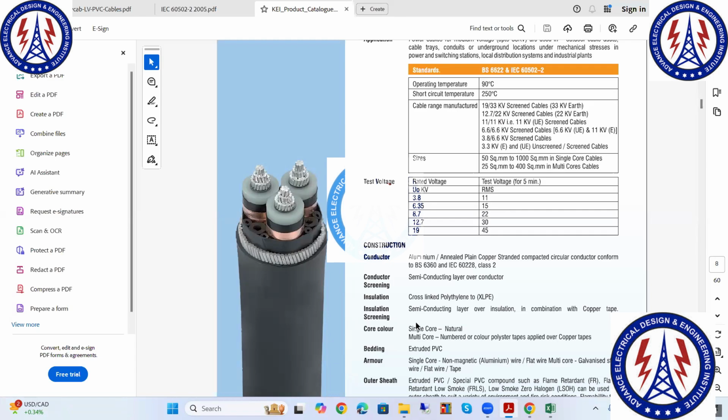In case of high voltage, this single insulation cannot confine the electrical field within the conductor. It may puncture. That's why another layer is added. This is one layer, this is the second layer, so that in case of high voltage also, this insulation will not get punctured. Because a single insulation cannot protect it in case of high voltage, that's why the vendor is adding another layer.